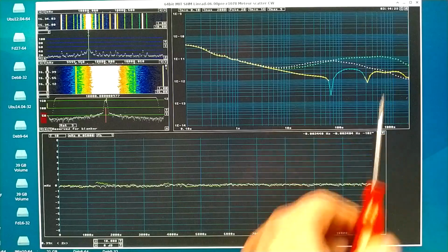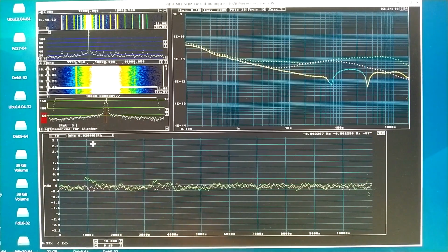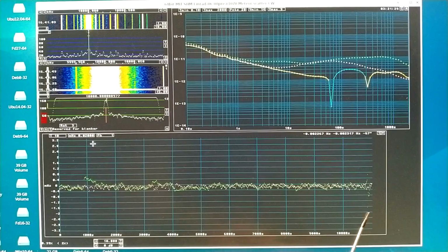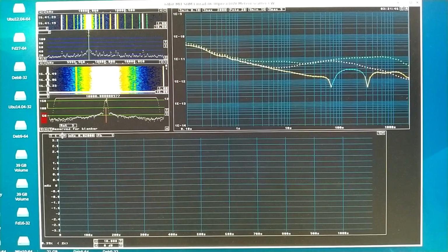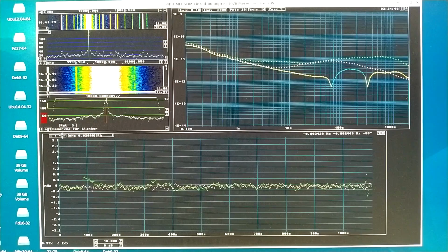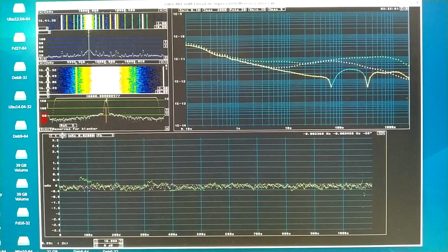And then at 1000 seconds it was here, and the red curve is essentially the other LPRO, not off by very far. So I set the scale to see this better, and then I have hit the channel 1 oscillator gently with a hammer a couple of times, and you can see the frequency went up and it went down. And here is a green dot also. So to see better what happens, I will increase the speed of the graph by a factor of 10. It was 10 seconds per pixel. Now it is 1 second per pixel. And I will repeat the procedure with a hammer on both channels.